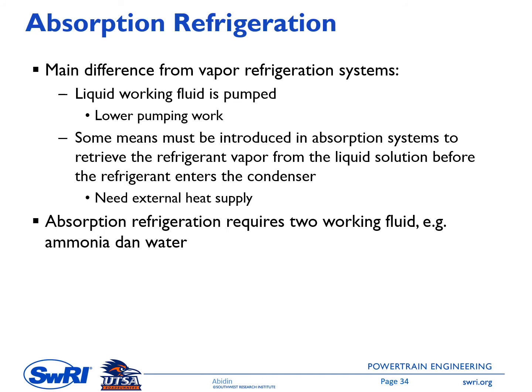So this means that the absorption system will require lower energy from outside. Why? Because pumping liquid requires much lower energy than compressing a vapor.